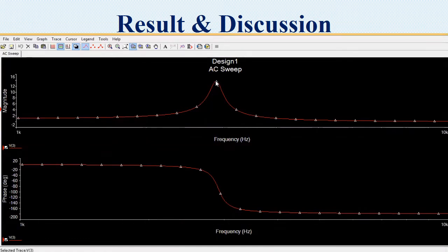And after reaching this point, the resonant frequency point, the impedance of the circuit equals the resistive element only. We have the capacitive and inductive terms, which are equal in magnitude and opposite in phase shift. That's why they cancel out each other's effect, and at the end we have just the resonant frequency occurrence where the impedance of the circuit is equal to the resistive element.